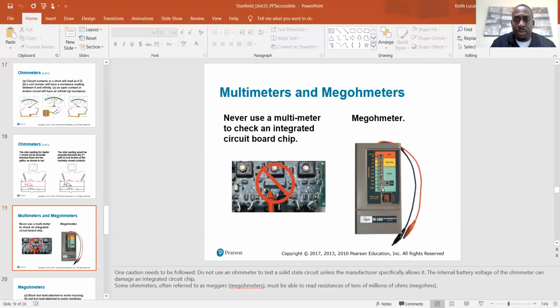Here in the green area is good, where it says good, and up here in the yellow area it says caution, and then up here in the red it says bad. So if the lights stay within the green range, then you know your compressor is good. If it gets into the caution range, that's the point where I want to show the customer, yeah, your compressor is operating, but it's not performing, and it's at the end of its functional life. The meter is telling them right there to be warned that the compressor is at the end of its life. And bad, usually you'll know if it gets to that point because it won't work.